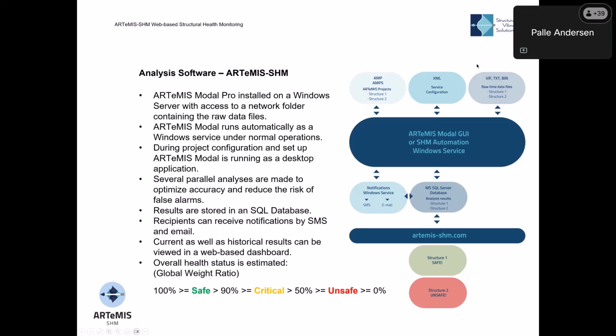All of this is, of course, configured by the graphical user interface, and it's saved down to an XML file that the service is then using to figure out what to do, which structures to analyze, and when to analyze them, and so on. As I said, results are stored to the SQL database here, and along with mode parameters and damage indicators and so on, there are also alerts being stored if something has triggered an alert inside ARTeMIS Modal.